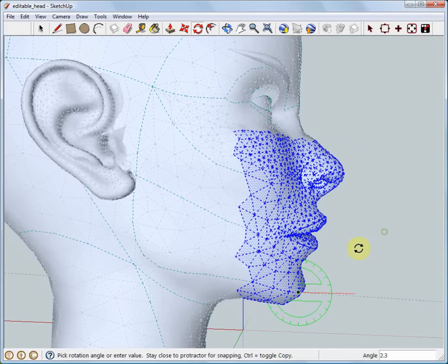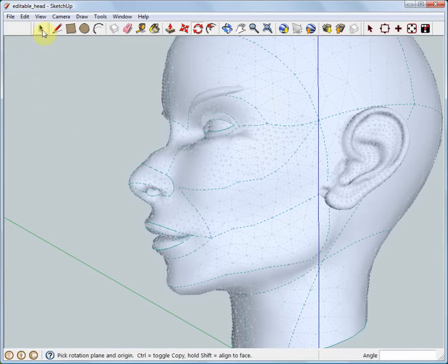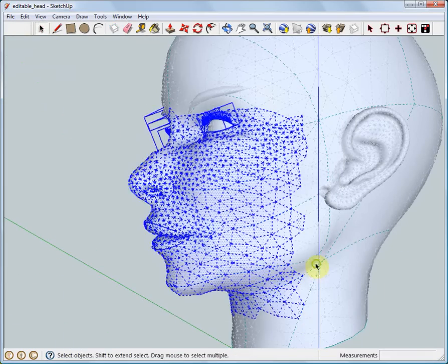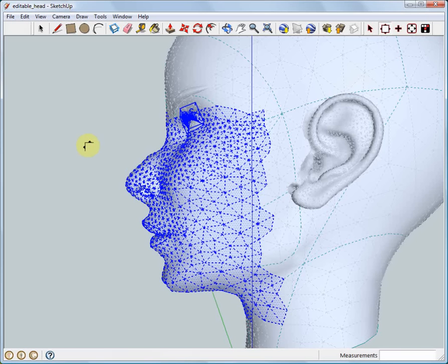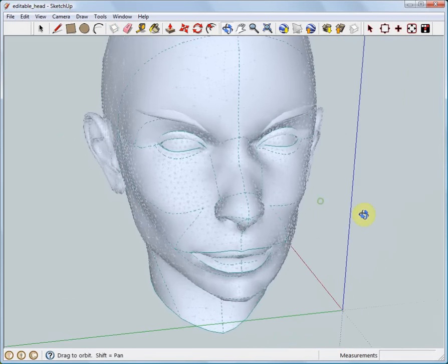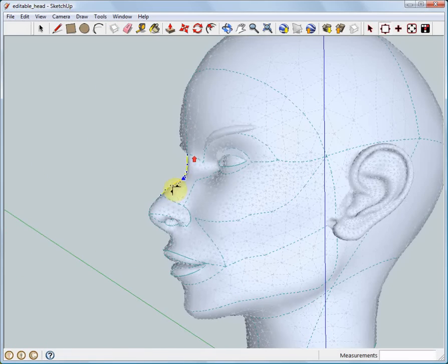We rotate the selected portion downward a little so that we have, say, a slightly different bone structure. Then we select the affected surfaces and smooth them again. Notice that only edits on the control curves have any consequence, as the surface mesh is reshaped according to the changes in the control curves during the smoothing operation.